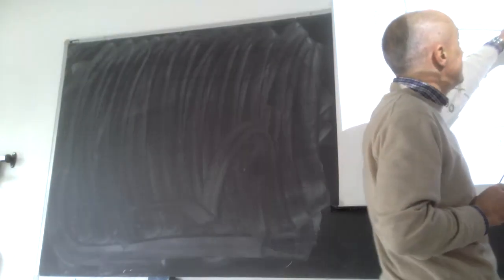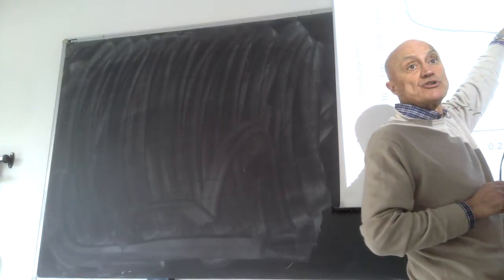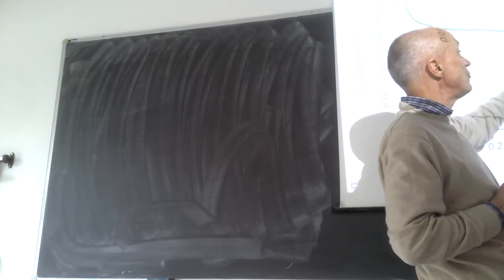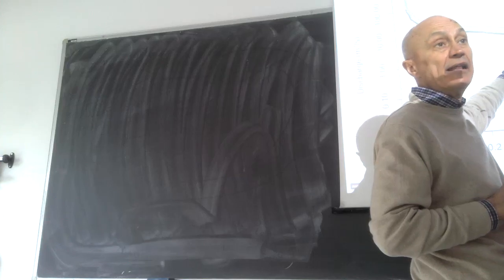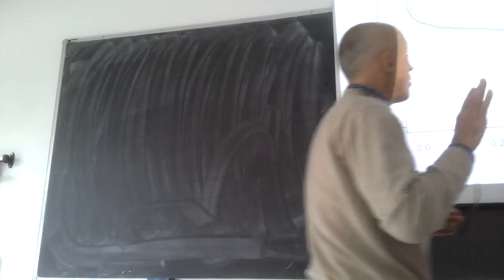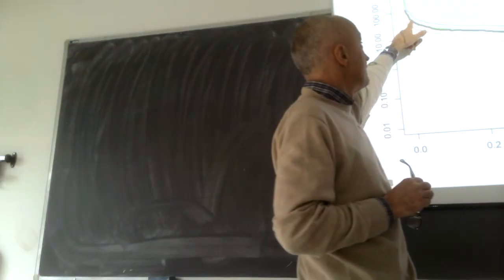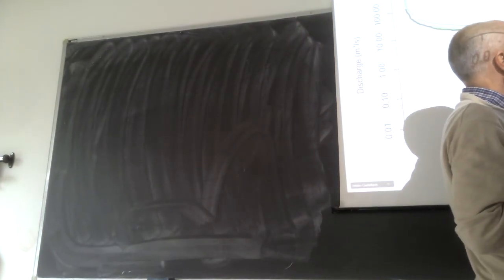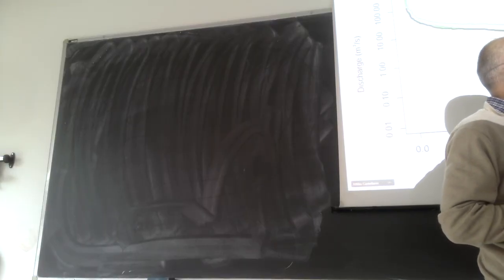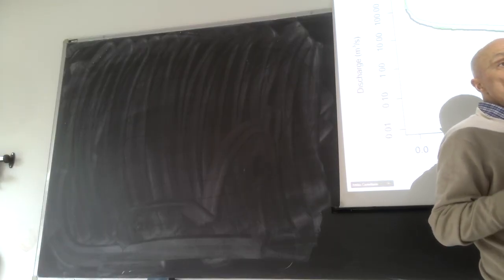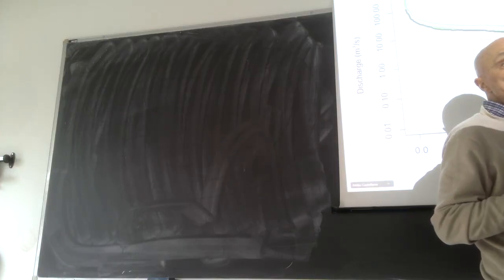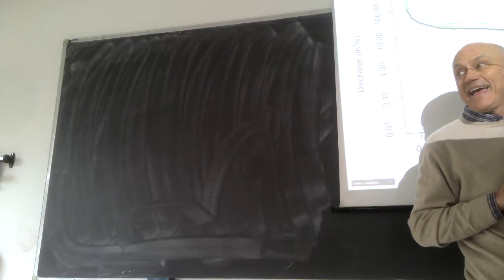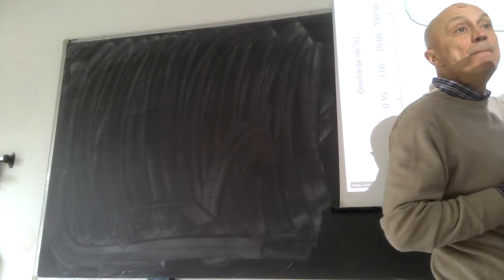What I want to point out is that the indication of a typical, from a climatic viewpoint, regime, you can retrieve from either the period of record and the median annual flow duration curve for a duration range which is intermediate. You see, the 2 of them are very similar, up to the tails.